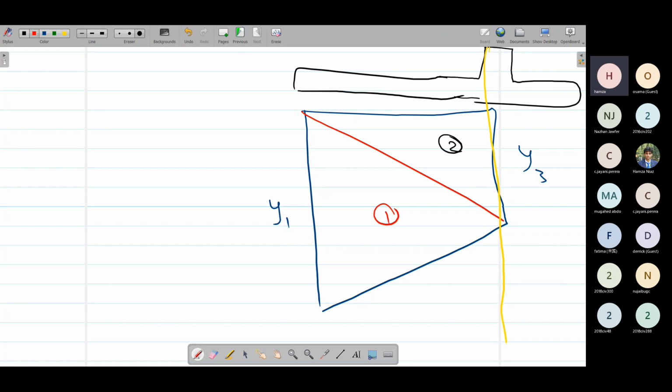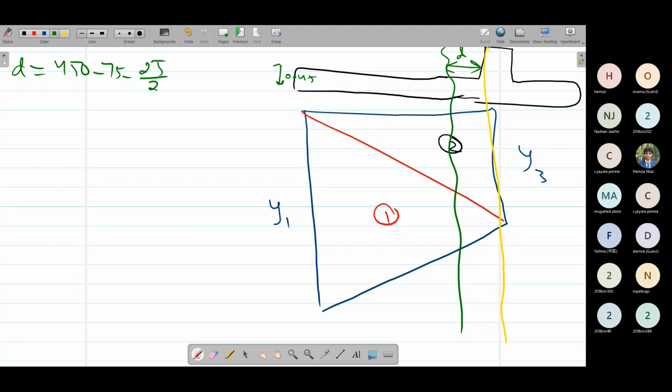So the shear value of the toe portion is again acting at d distance from face of the stem. First calculate d value. The d value for this now would be like this. 0.45 is its width. For toe, the width of the concrete is 0.45. So 450 minus 75 minus half dia. So this way we can get this d value. This is 362, I think. 362, something like this.